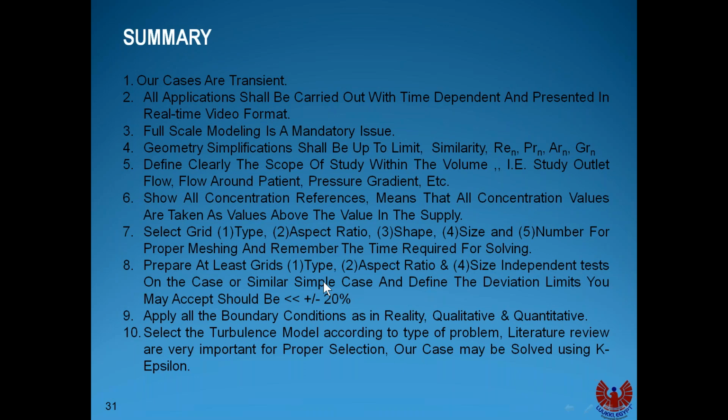So again, in the order we have to declare that you have to put in your model a full scale model, and the simulation or the modeling will be time dependent. Third, the geometry shall be installed completely in detail, and you can make some simplification of the geometry, but you have to keep the main parameters of the similarity principles as they are, like Reynolds number, Archimedes number, Stanton numbers, all these dimensionless groups.